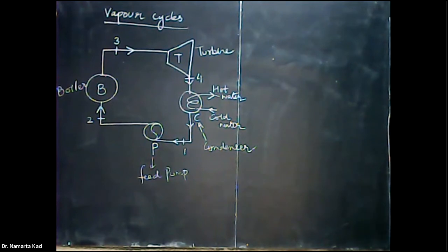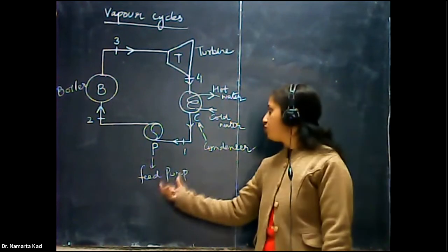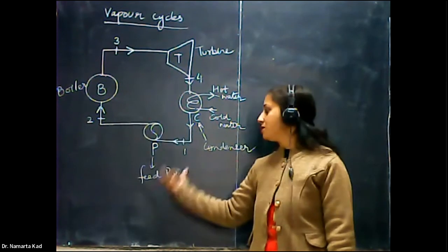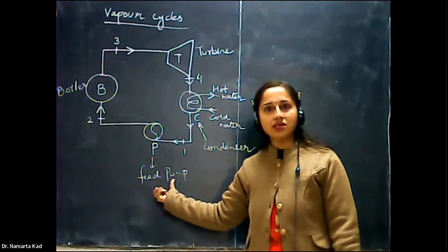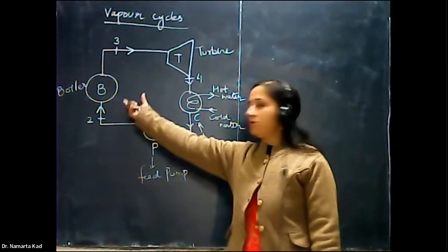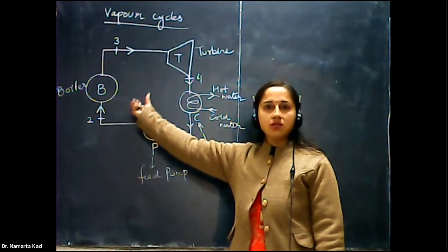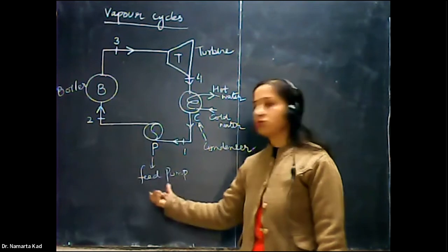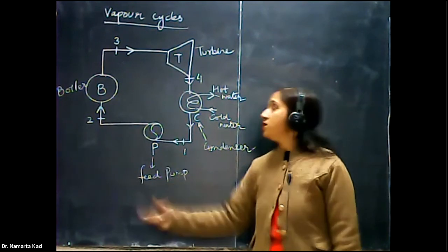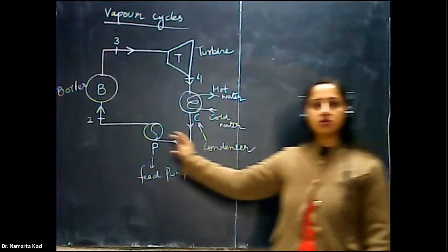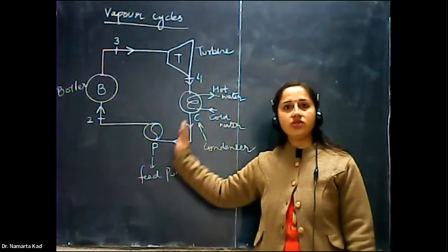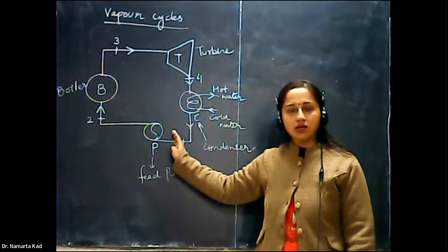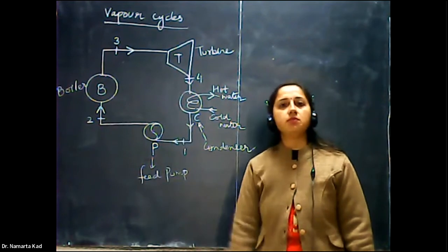Okay, so what is the function of the pump? One is to feed the condensate back to the boiler, and secondly, it increases the pressure of the condensate up to the pressure which is required in the boiler. So this is the complete process, or the complete cycle which continues, that we call the thermodynamic cycle, working in thermal power plants.